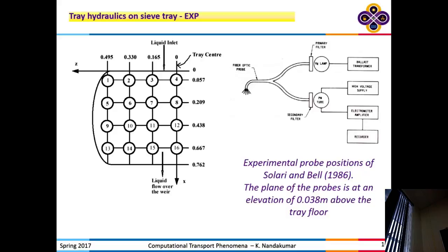Is it average? For example, if I give you a pitot tube and say, go and measure the velocity profile in a circular pipe, right? So the pipe is something like this, and a pitot tube. You know what a pitot tube is? It's essentially a tube like this, and if the liquid is flowing like this, you point it in this direction. So the kinetic energy is converted into pressure energy. So you get a pressure signal with a manometer there, right? By attaching to this, for example. So from that, you can calculate what the velocity is at a particular point. When you move this across, then you can actually get the velocity profile.